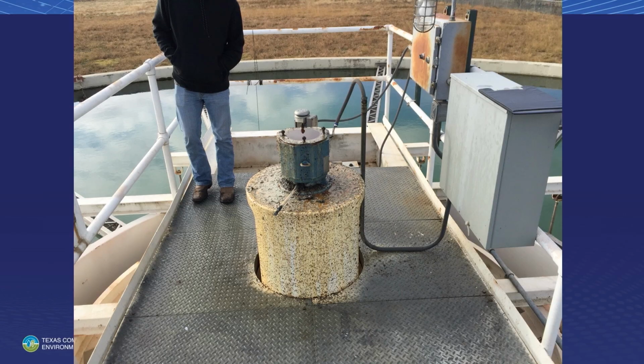Solids contact upflow clarifier. If you don't have something driving that internal fan inside that solids contact upflow clarifier, it ain't clarifying. There's no recirculation inside that cone. Well, if there's no circulation, there's no flocculation. If there's no flocculation, you're getting pretty bad settled water coming off the top of that thing.